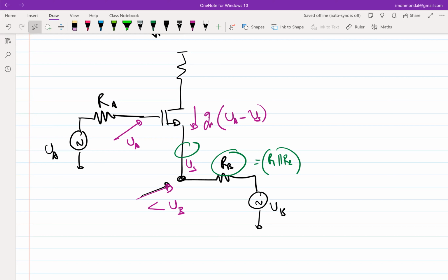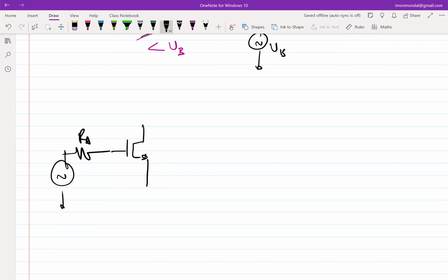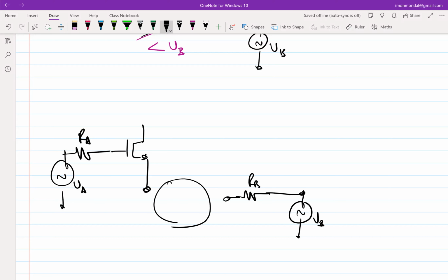Okay. So if we don't want this loading to play spoil sport, what are the other possible scenarios? How can we fix this? We still want to make that op amp, but we want this voltage to be that. I don't want this source to load the voltage source. So essentially what I'm asking is, there's no problem with this guy. VA is not getting loaded, but I have another source, VB, which is now getting loaded. Can I put something in between here so that it doesn't load VB?